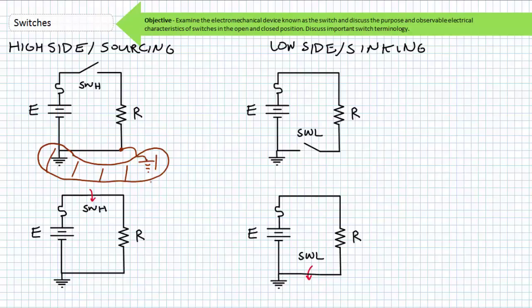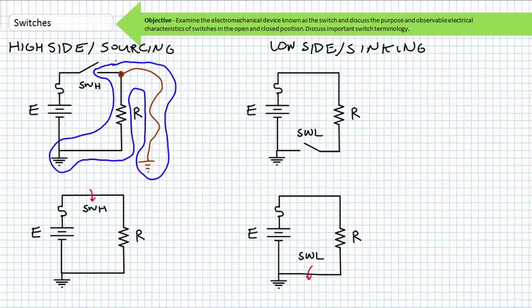Though as we'll soon learn in the circuit protection lecture, current would be traveling through an unintended ground path, and this leakage current could be detected and resolved with a ground fault current interrupter, a GFCI. Consider a different location of the errant wire where it touched the top terminal of the electrical load. If the switch is open, nothing would happen. The electrical load experiences ground potential on either side of it, and there is no voltage differential across it. The electrical load would not energize.